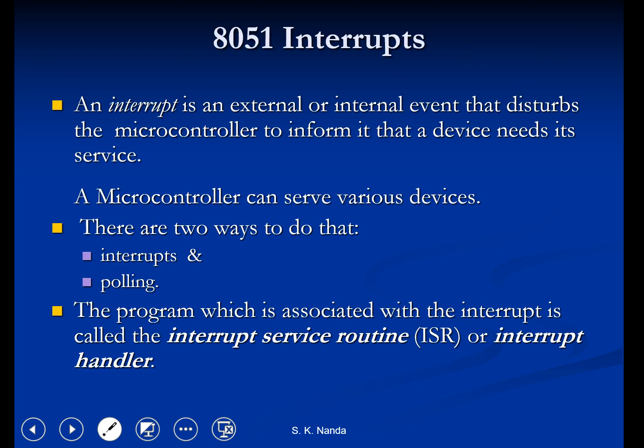Now talking about interrupts, the most powerful and important feature of the 8051 microcontroller is its interrupts. In most real-time processes, to handle certain conditions properly, the main task must be halted for some time. It takes the required action and then it must return to the main task. For executing such types of programs, interrupts are necessary.